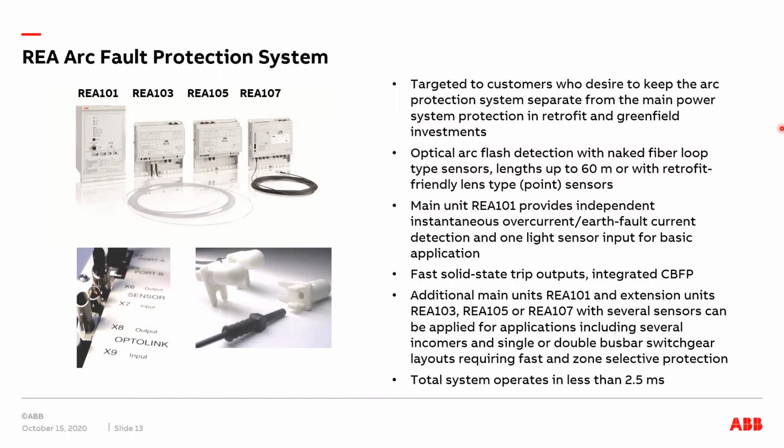And then, as we heard, time is critical in arc protection. We have also fast solid state trip outputs to give as fast tripping as possible. Mechanical contact output relays are not that fast, but we have solid state trip outputs which are directly capable to trip circuit breakers. And to secure the tripping, we have also integrated circuit breaker failure protection feature in REA system.